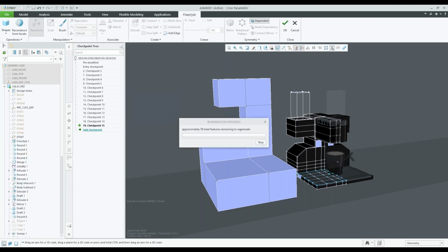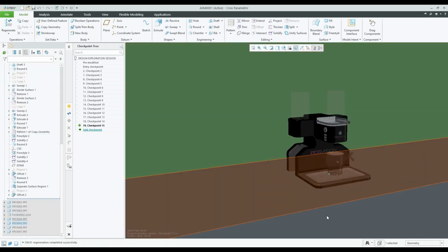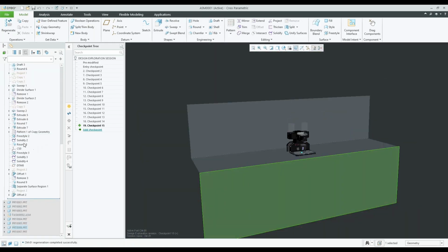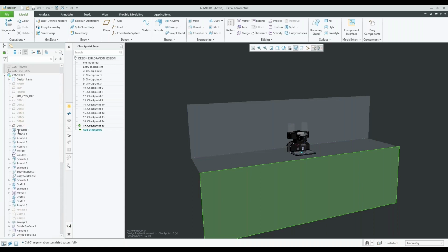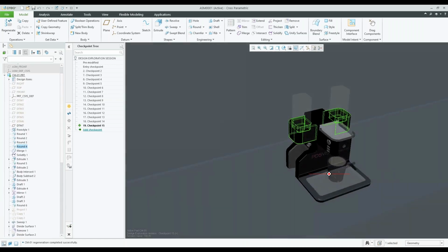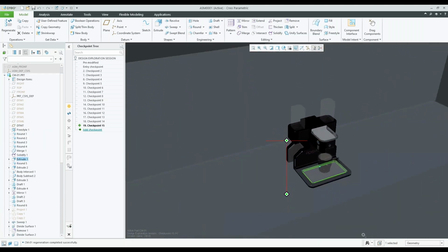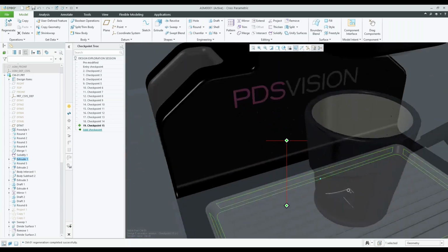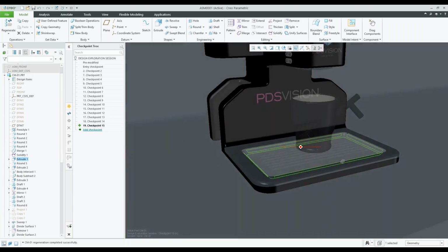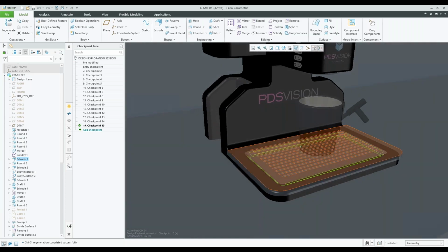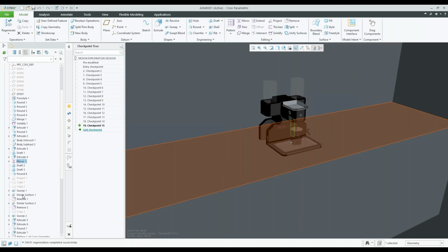So just click on cancel here. All right, so that brings me here. And you can see, aside from that base feature, I've got some rounds that I applied. I'll zoom in here, some rounds there. There's an extrusion that I made there because I want to have a little recess here in the model to collect water. So I built this little tray. I used the multi-body tool to do some Boolean intersections. Did some mirroring of some things, and divide surface.